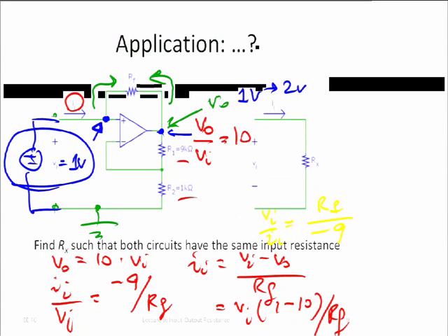So this whole circuit looks to this source, to this Vi, like all of this stuff. It acts just like a resistor Rx, and the value of this Rx is minus 1 kilo ohm. Okay? So yes, you cannot go to Radio Shack and tell them, I want a negative resistor. But you can go to Radio Shack and tell them, I want a couple of resistors and an operational amplifier, and then you can build this circuit, and you actually build a circuit that implements a negative resistor. If you also stick a battery inside and put it in a nice black case that nobody can look through, give it to somebody, and he measures it, he says, well, what you have here is a bloody miracle, it's a negative resistor.